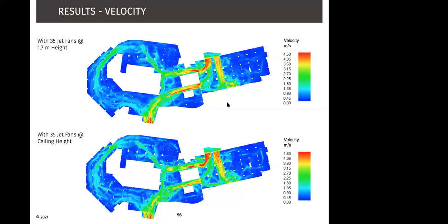So going back to the behavior of airflow, the air will always choose the shortest route. Because it's being pulled across from this shaft to this shaft, and this is almost 113,000 CFM of air being pulled in, it forms a wall of air. So there is very limited air movement in this area. And considering that the CFM for these jet fans is quite small compared to the CFM which is being pulled around, the wall of air is actually overpowering those jet fans.